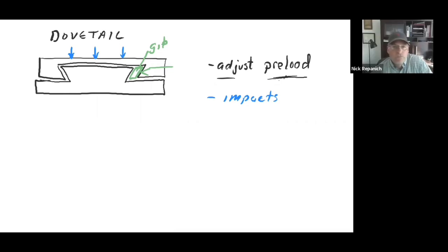No, you could use heat and cold to control dimensions. Anything that you can think of to control dimensions is what you're after. So in general, yes, you're going to have to think about whether you could use a taper fit and tighten it so that it's got a slight taper. That's adjustable then. If you just had one size shaft and one size bearing and had them go together, it's going to be very temperature dependent, especially if it's anything but steel.